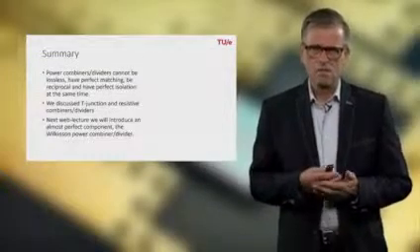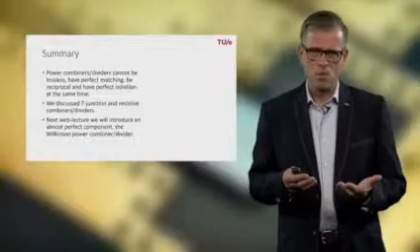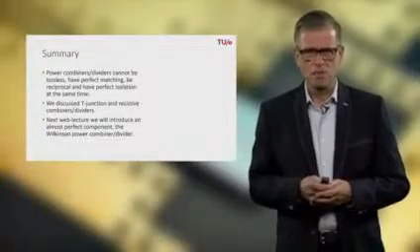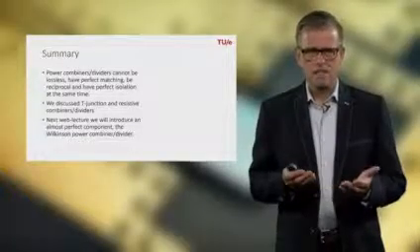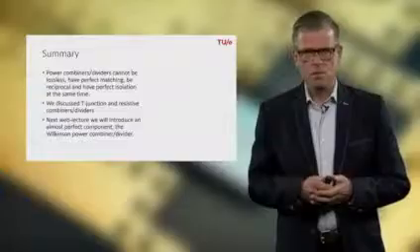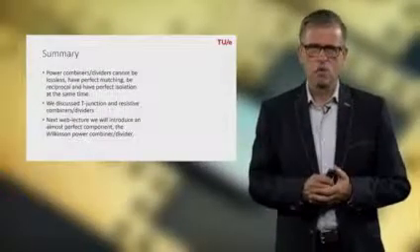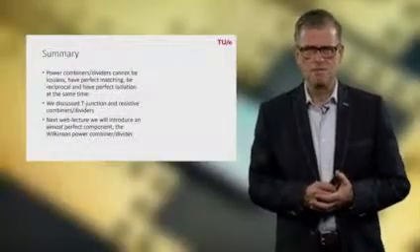We looked into the simple T-junction divider and showed that it has poor output matching. The resistive divider has good output matching and input matching, but has 50% of loss. And in the next web lecture we will introduce an almost perfect component, I would say, and that's the Wilkinson power combiner or divider. Hope to see you back again.